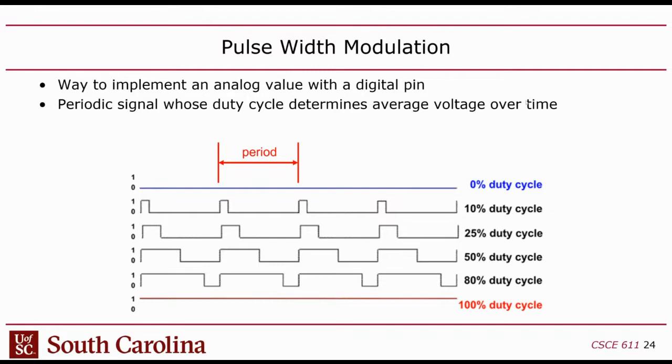And so when you take a signal like this, assuming that the period is short enough, and you run this through a low pass filter, basically a way to take out the high frequency components that are a result of these sharp digital edges, the transients going from 0 to 1 and 1 to 0 inject high frequency components.